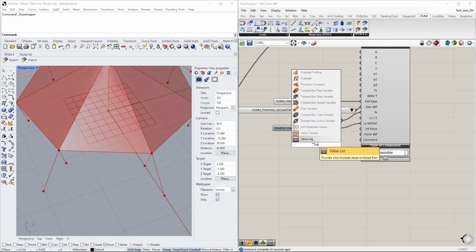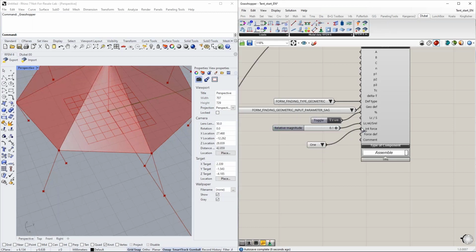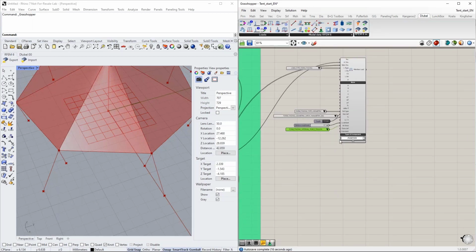And it should be a tension related form finding load. We also have form finding for compression, or structures under compression. This is also possible. In this case, I will, however, link it to my tension forces. Okay, so the first load is defined.